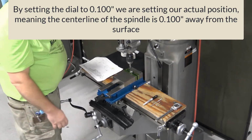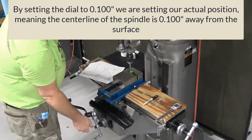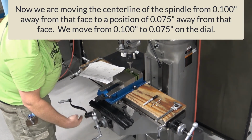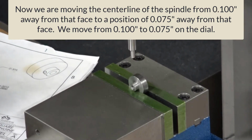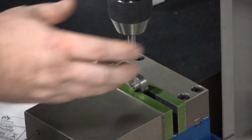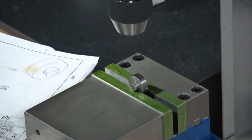Now, if we look back at our drawing, it represents that we have to be 75 thousandths away. So we're going to move from 100. Remember, we were turning this counterclockwise, so we're going to continue on to the 75 thousandths mark. Cutting forces aren't terribly high, but I'm going to lock my table in nice and securely. Take my edge finder out.